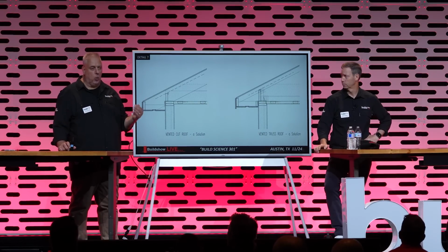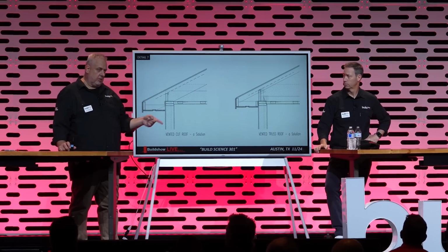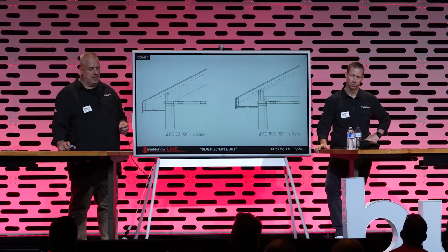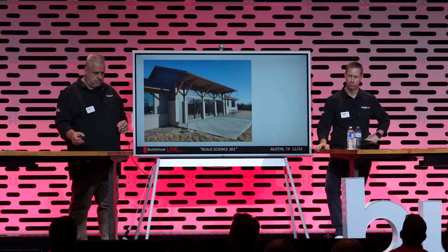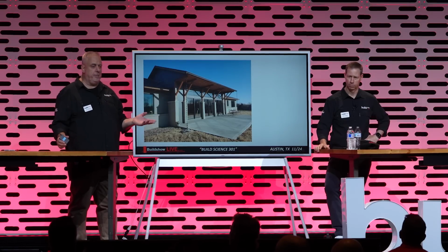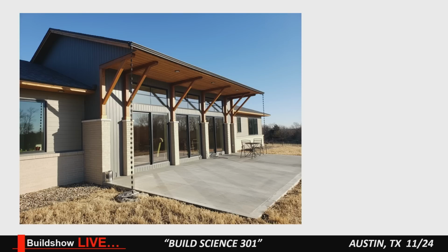We get zero wind washing, which is the effect when air goes up and cuts into our insulation and makes it cold at the perimeter. All right? When you have tall walls and you want to protect them, you put big overhangs. Yeah, you do. So that's a 66-inch overhang over the top of that wall.